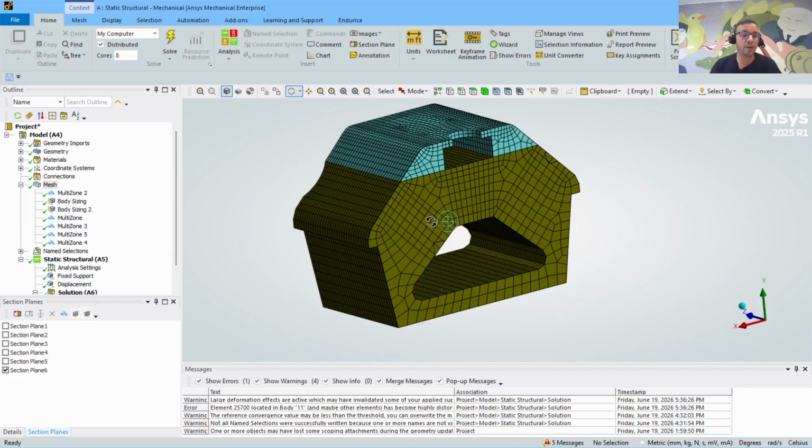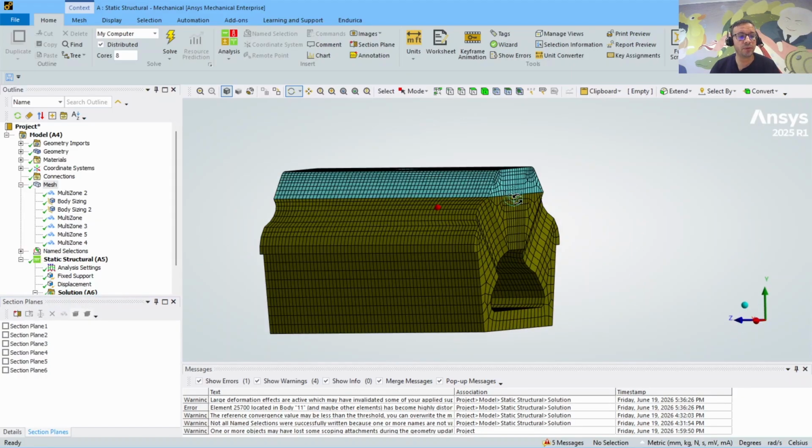Even though bulk elements are not usually exposed to very high strains, it may happen because of distortion that some very high artificial strains occur, which corrupt the fatigue results as well. Something that we really don't desire. This is just to mention why we have decomposed this model.